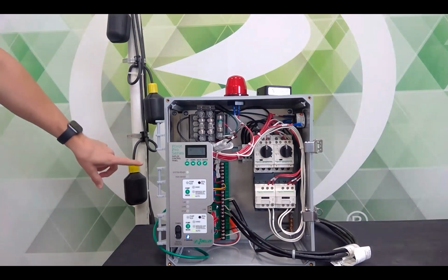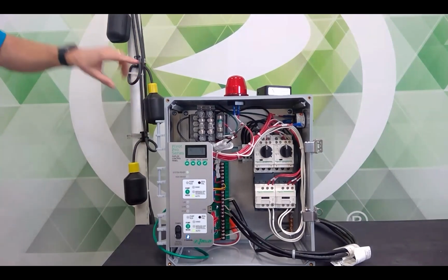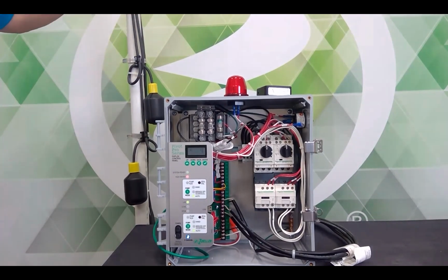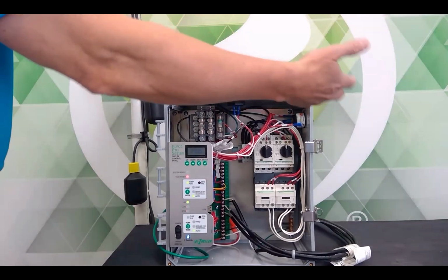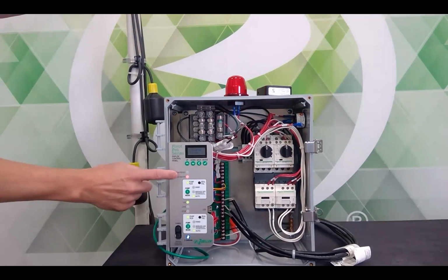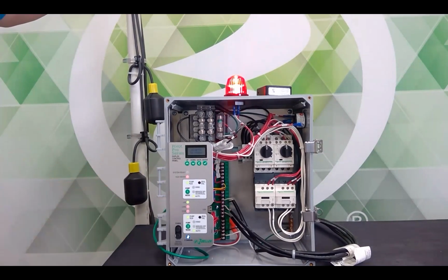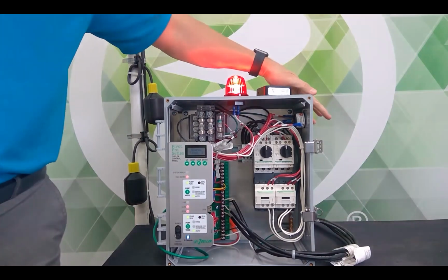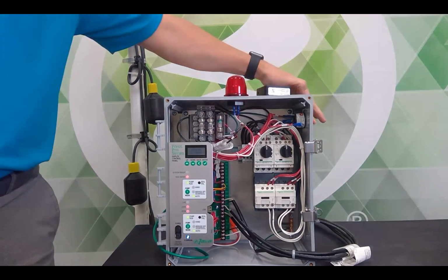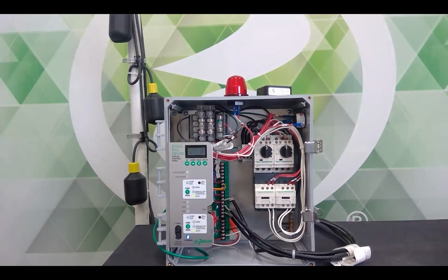Same thing here. If I've got a stuck stop and a stuck lead, I go to high. Again, I've got an alarm. I've got a horn. I've got a high water red. I've got stop and lead blinking red. Now, when I let it down, it's going to let the pump run for 20 seconds. Actually, I reset it, so it didn't go 20 seconds. But I just wanted to show you that.